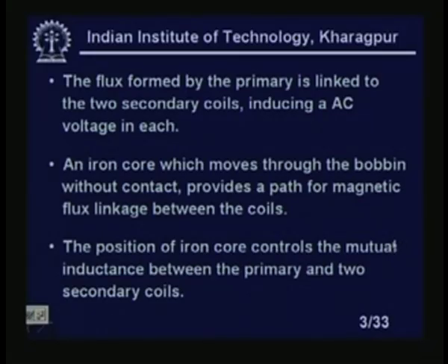Usually, in some cases, we put the entire LVDT assembly under another casing, so that it will not be influenced by external magnetic fields. Obviously, it depends on the magnetic fields. So, we put the entire assembly in a casing so that the external magnetic field will not affect the output voltage, because we want our output voltage to be a function of the position of the core of the LVDT.